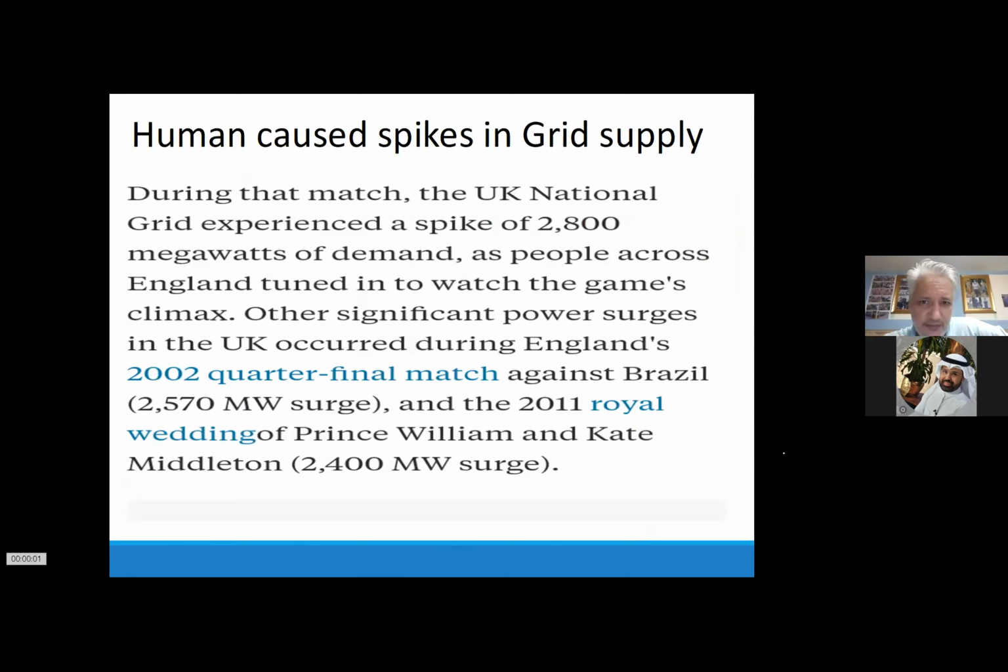So you should think about making horizontal lines, from the left to the right. In some areas it doesn't work, but then you should split them. At the bottom, like I showed in Dubai, you have 55 degrees on the corners of the roof, and when you have a breeze, you have 40 degrees. That's like 15 degrees difference, and the inverter has to match those differences.